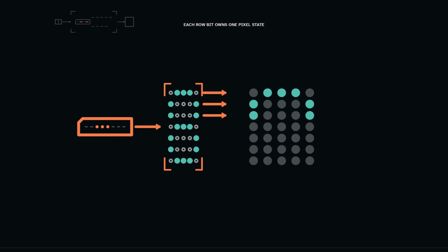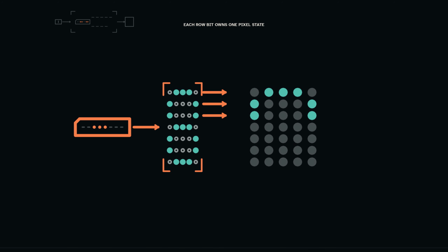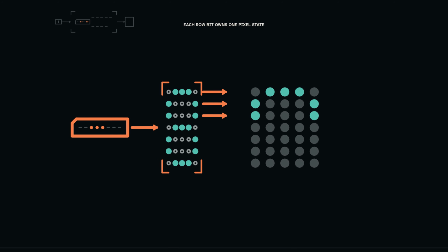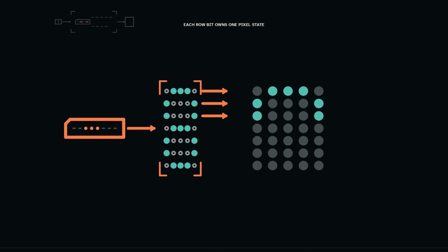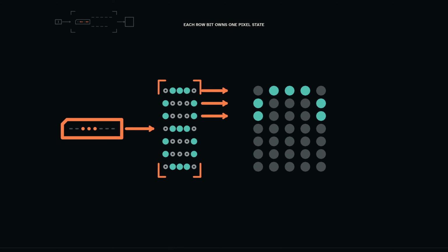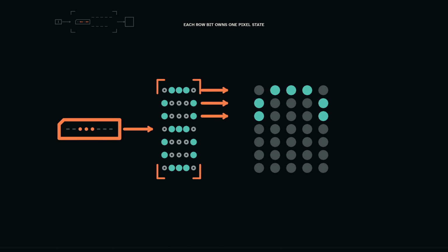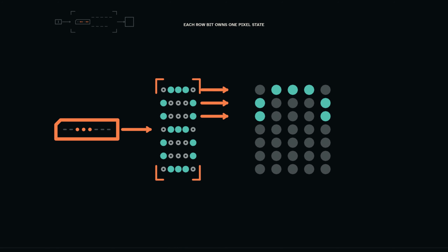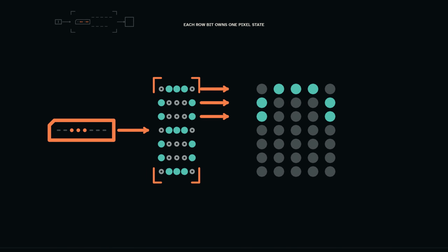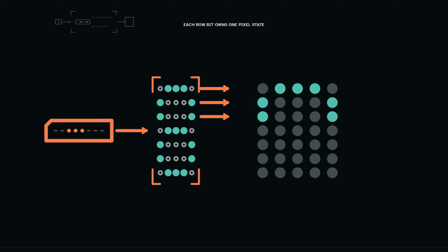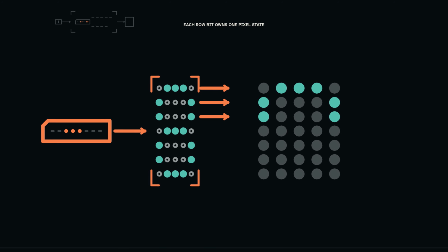The adapter presents a row mask and a row address. Selection circuitry opens the corresponding line of the pixel array, and each bit determines the requested state for its column. Repeating that operation for every stored row builds the bitmap from top to bottom. The pixels do not read the character code, and the processor does not draw the curves of the glyph. One mechanism selects glyph data, another maps that data onto physical display elements.